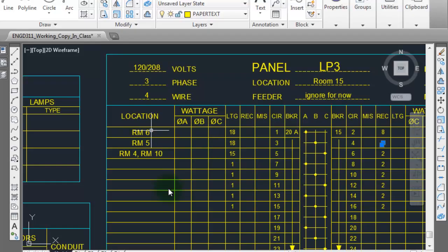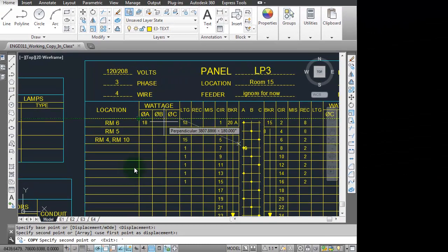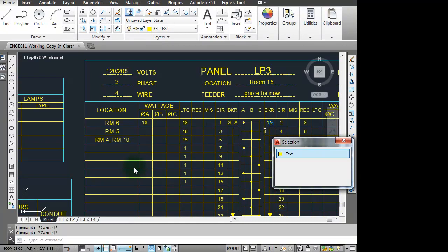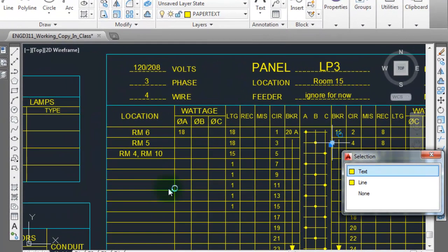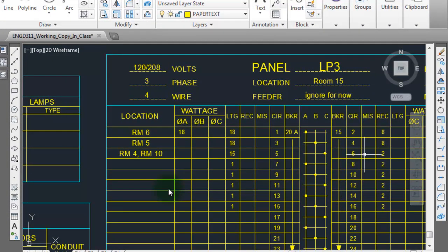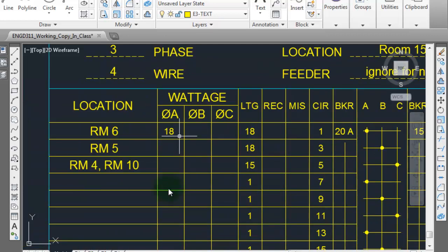So we go back to AutoCAD, and it's 48.3 times 18. So let me just grab my calculator here. I have 869.4 is my answer there, 869.4. That's 48.3 watts multiplied by the number of luminaires that I had for that. Just delete that, I accidentally copied text over.